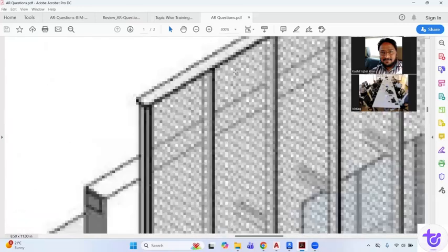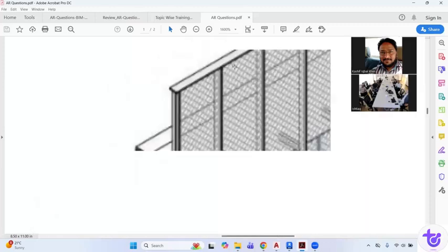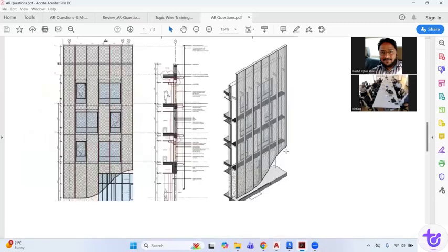For example, this one loop, I am making as a 3D physical model. If I repeat it 1,000 times, definitely it is going to reduce the speed and increase the file size. So in that case, we'll have to make it a separate model and link it as a mesh model.